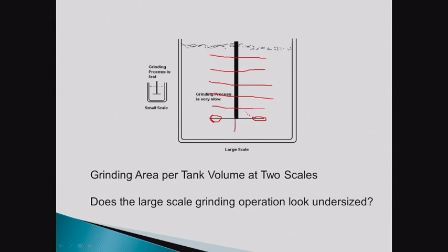He also extended the impeller shaft down and put one down there. So you increase the grind areas for the large tank. The grind time was reduced from 24 hours to 1 to 2 hours. He was quite effective.